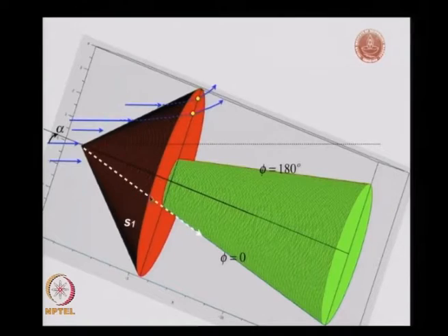Okay, evenly spread out. It's not going to do that. So what we will have is that the flow here, we will have basically two streamlines, one going right down to the bottommost part of the cone, which is shown by this white dotted line here, okay, and we will have one more at the top. Other than that, since the bottom of the shock and the top of the shock are different because of the shock wave angle, this is the stronger part of the shock.